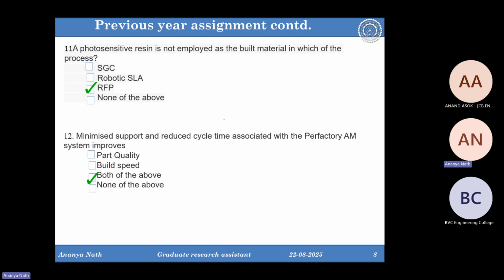Okay. Because when you have to cut the support from the build, when you cut the support, there will be some marks of the support, residue marks and dents in your part. Imperfections will be there. So that's why the surface roughness and the quality will not be good in that portion. You have to go for further post processing for those parts. And in some geometries, the support will be so intrinsic that after removing the support, you can't even go for any post processing to cure that surface. So that's why.